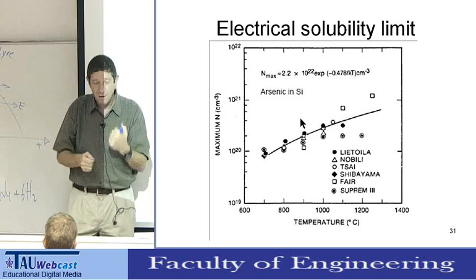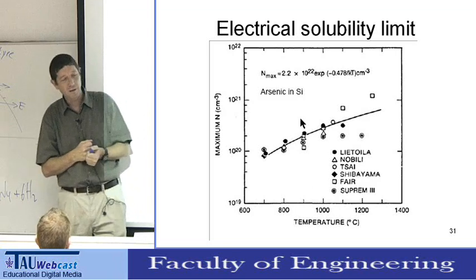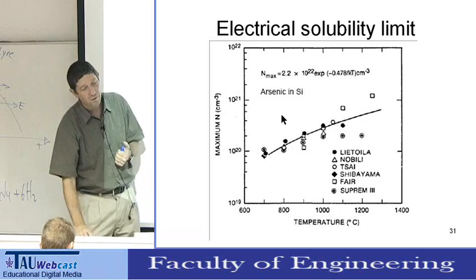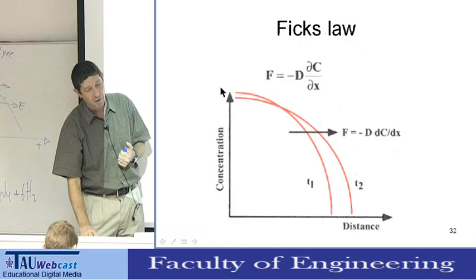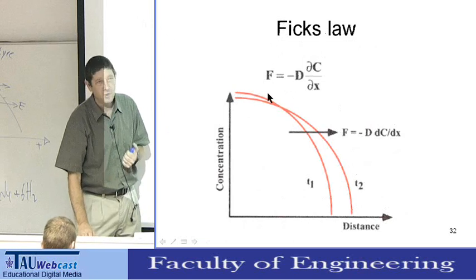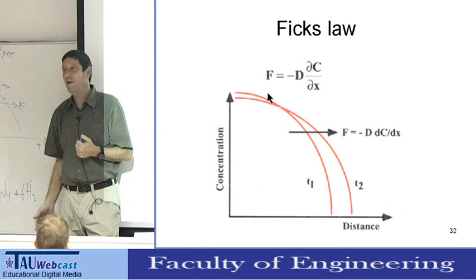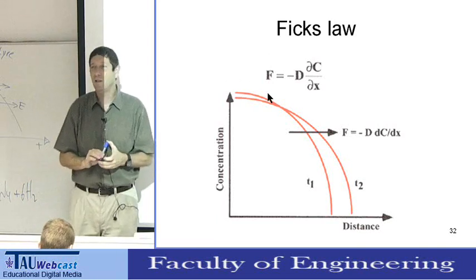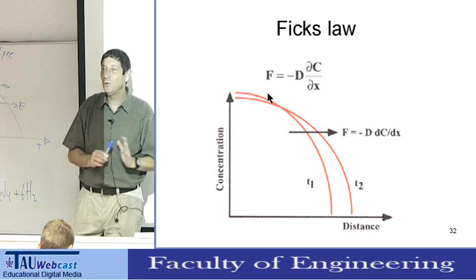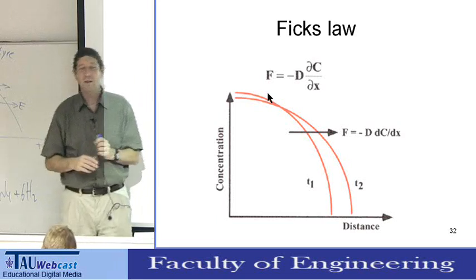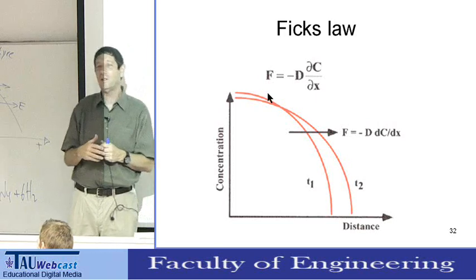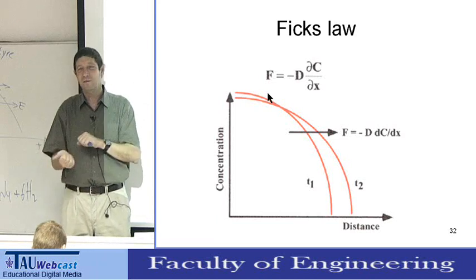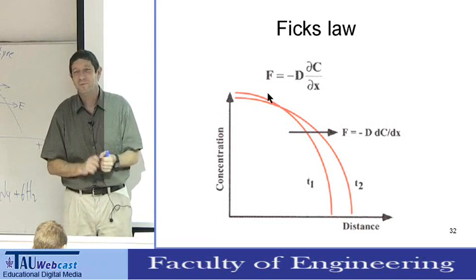This is a big problem in material science: how to introduce dopants above the solubility limit. Don't you create stress? You create a lot of stress, and then the reliability will go down. It's a good point. A good process still does not exist. There are some processes available, but they introduce defects, and then you have to decide what you like more.